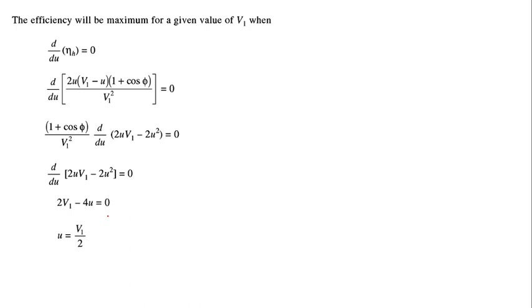In the case of hydraulic efficiency, we need to find the maximum value we can obtain, and the condition under which we get the maximum efficiency. So we take the derivative with respect to the velocity, to find at what velocity the hydraulic efficiency is highest.